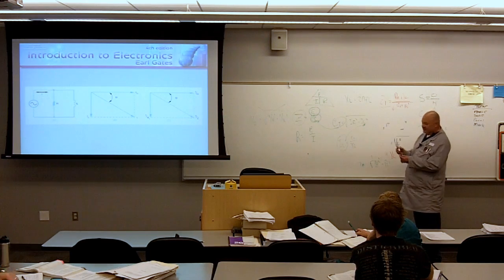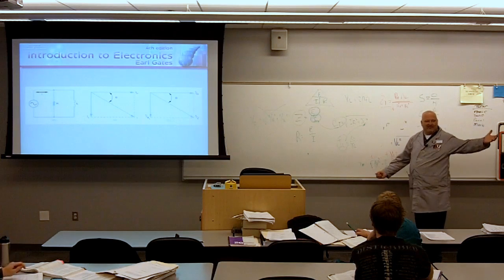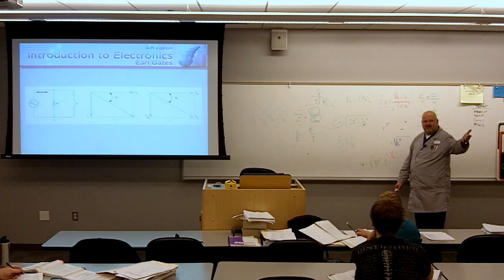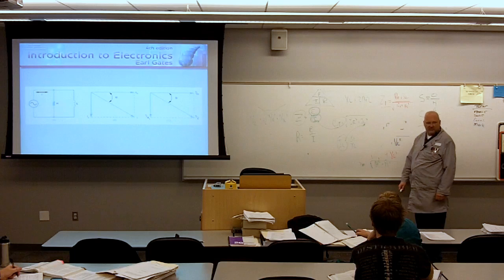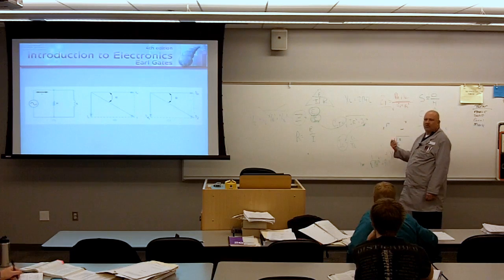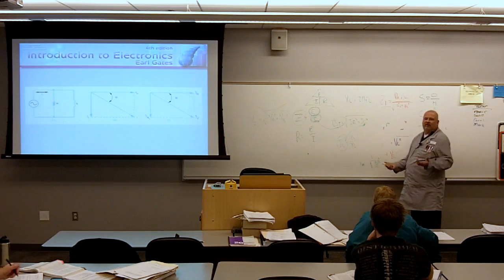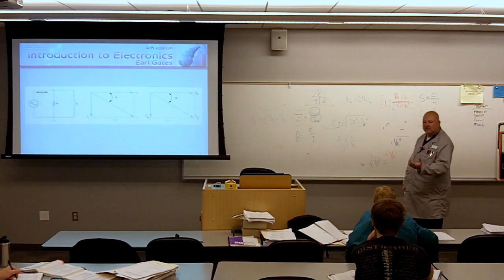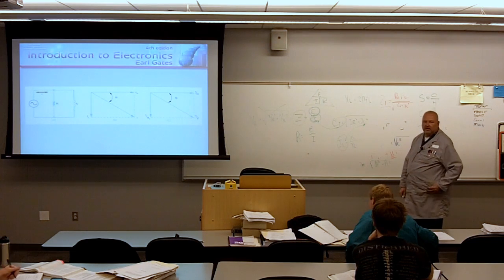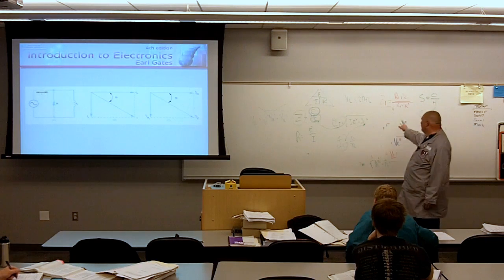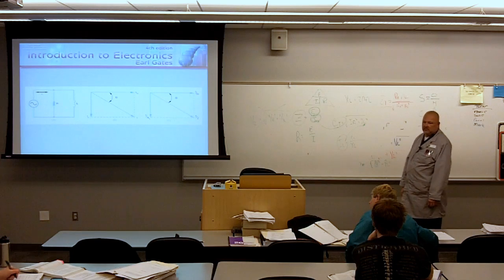This is another way that you could solve that ZT. And you already know how to do it. Because in DC, you all remember this formula, product over sum, right? So no longer are we dealing with the product over sum. We're dealing with the product over sum, but we have to now deal with the product over the vectoral sum. So if you really want to have fun with Z, calculate it out this way.